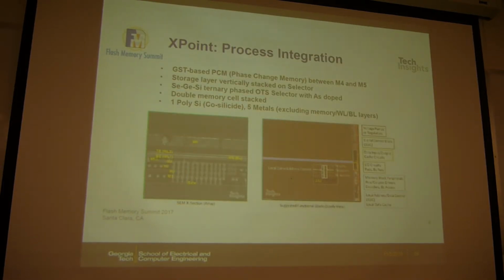And then they did further materials characterization of this one. And by the TEM image, the transmission electron microscopy, as a cross-sectional view, you will see this kind of cross-sectional view for the chip. So the corresponding layer, those two layers, corresponding array, is on the top. I think it's between metal 4 and metal 5 here.